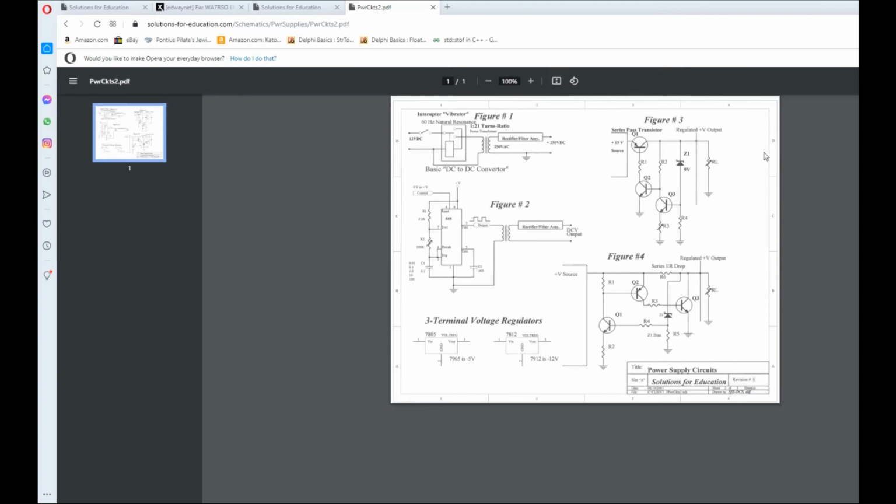Well, sometime later, my wife happened to hear this kabowie in the other room. She went running in there to find out what was going on. The 2-year-old son was long gone, and she could see it was turned on, but she couldn't see any smoke. By the way, I took it apart later and found that a capacitor had given up the ghost and shredded its innards all over the inside of that ARC5. What happened was it was this guy right here. When he pulled this, the voltage regulation went to pot, and instead of 250 volts, it went up to 425 volts. And the ARC5 says, this is more than I want. So therefore, it blew its cork.